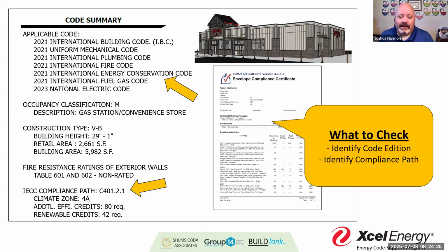Now, I'll tell you the one thing, and I did this on purpose, the one thing that drives me crazy is when I see international, especially in a state like New Mexico, which has a statewide code. This is where I would prefer to see a reference to the NMAC, right? I'd prefer to see that, because I want to know that you completely understand that you're not just taking a project, picking it up and dropping it somewhere in Roswell or Chaves County, right? That you actually understand that we have a specific set of guidelines, and that you've attempted to at least review to make sure that you've hit those amendments and specific changes that are reflective in the city, in our jurisdiction.